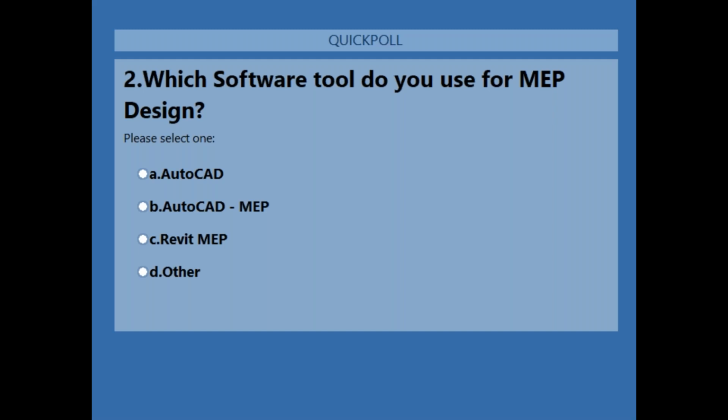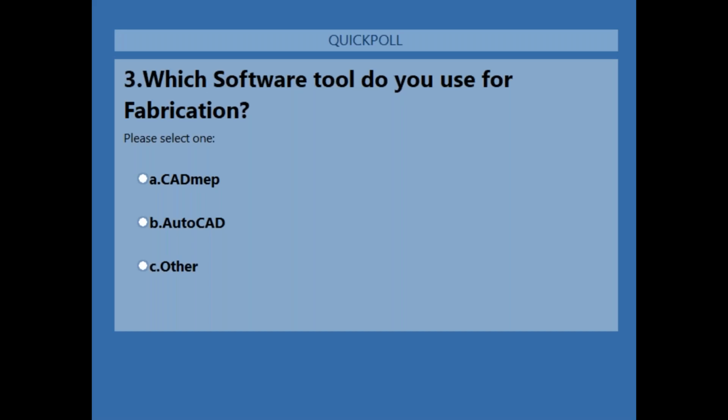There is a question: from which source does Autodesk Insight 360 take the weather data? Weather data depends upon our current location. Whenever you start a project, we need to define the project location. Based on the current project location, it takes the latitude and longitude, and the current weather data, forecast, everything will be pulled from the given location of your project. Then it goes to Insight 360.